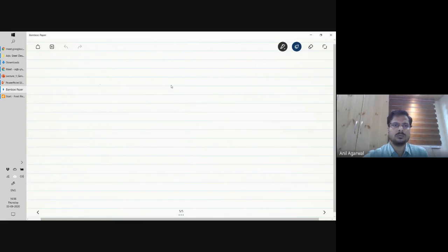As you may know, typically if I have any structural member, and this side is tension, so first I let it go to tension, I let it yield, and then I let it unload. Okay, so this is loading. First, this is the elastic phase, then this is the plastic phase, and then you may have an unloading phase. In this unloading phase, you are in elastic deformations. The new deformations are all elastic. Assuming that this slope is the same as this slope. Okay, so in this stage, let's say this is not a gradual change, this is a sudden change.